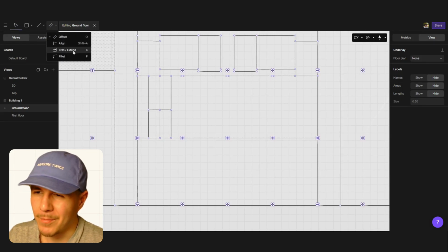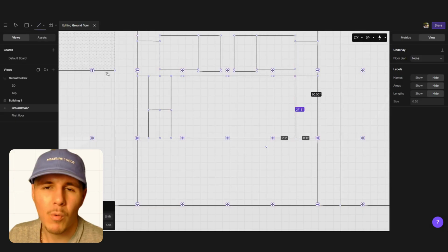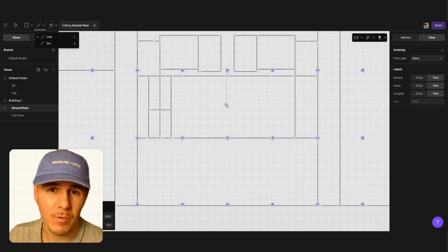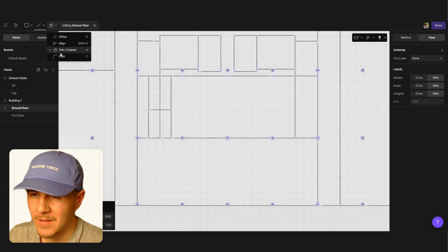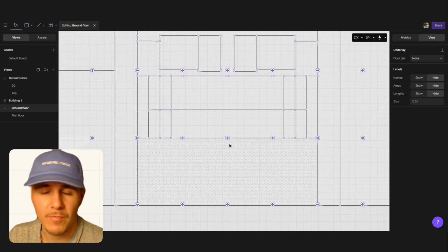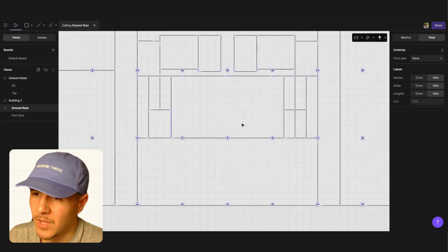I don't know why I do that, but it just makes more sense to me, to allow people wherever they are in your building to be able to egress out as close as possible. I feel like if it's more spread out, you're covering more ground. But there's no reason for your egress stairs to not be central if they are far enough from each other and if they cover enough ground, which seems to be the case here.